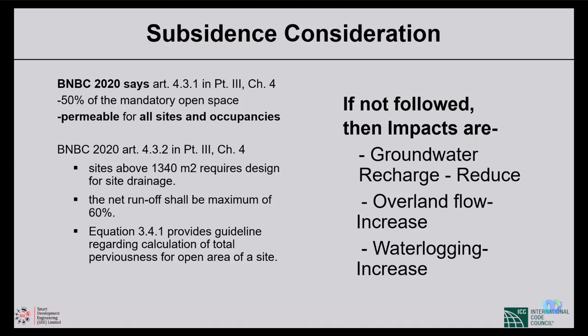Then subsidence considerations. When you're talking about settlements, the BNBC says in article 4.3.1 part 3 that 50% opening is mandatory. So why? There will be more recharge, more groundwater flow, no depletions, and ultimately less settlement, less subsidence. That's what we are talking about, the overall principles.